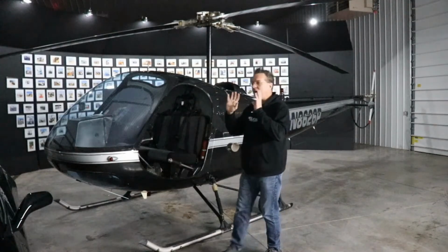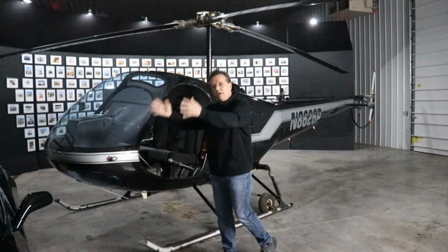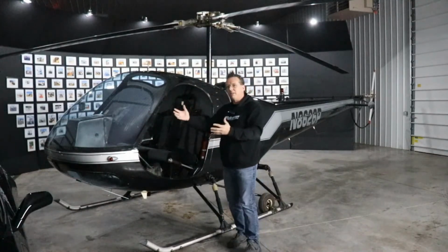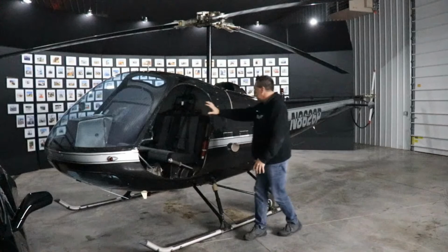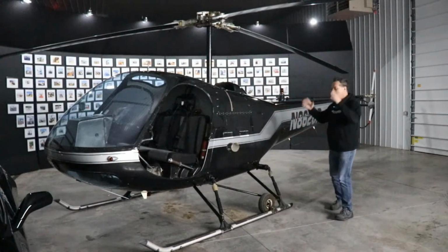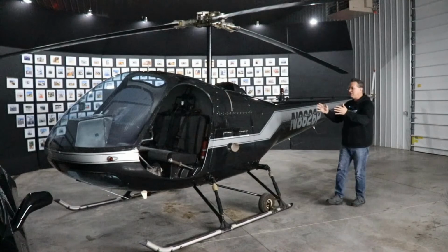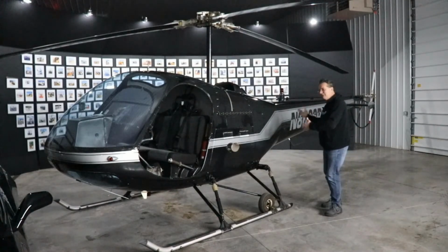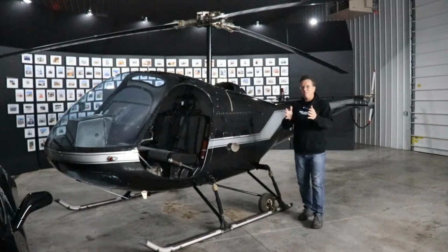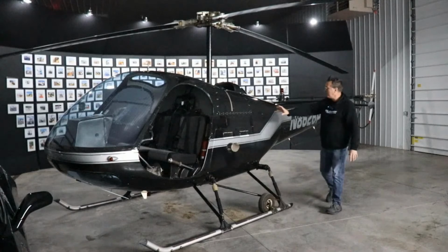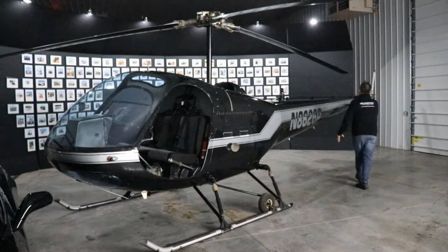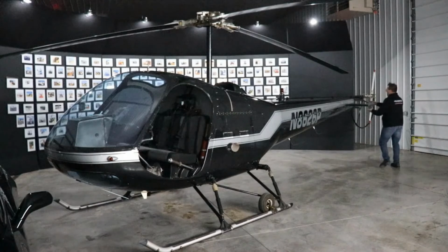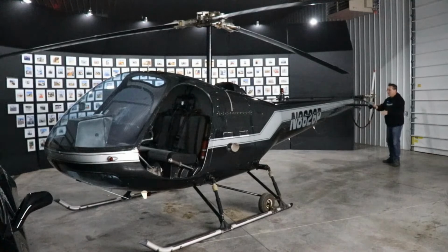It's not going to when you have a lot of forward airspeed, because streamlining the fuselage is simply the airflow going down past the cabin of the aircraft, and that nose is pointing into the wind, so even if you lost the tail rotor, it's not going to move much. It might move a little bit, but in forward flight, it's not going to move much because you have this airflow going all the way down the side of the aircraft, and you even have back here what we call a horizontal stabilizer. Some helicopters have vertical, some have horizontal. So you've also got stabilization back here as well.